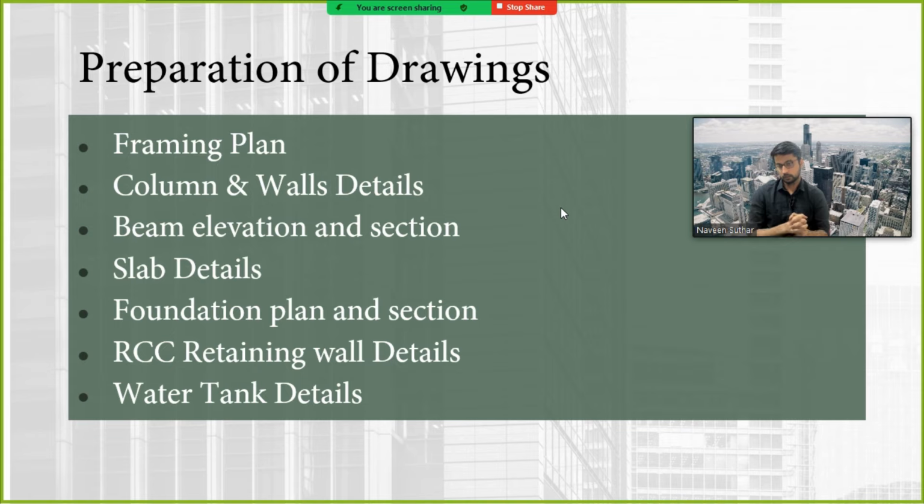In the detailing, we prepare the drawings for construction support and for the client review. We will prepare the framing plan, the column and wall detailing, the beam elevation and section, the slab details, the foundation plan and section, the RCC retaining wall details, and the water tank details. Every reinforcement detail we have to submit to the client for approval.